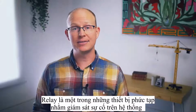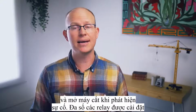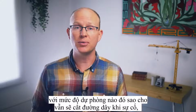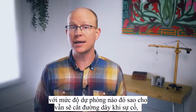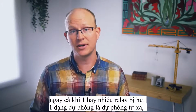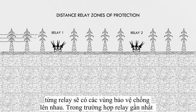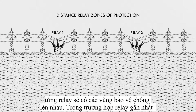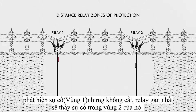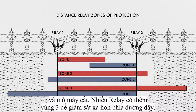Relays are sophisticated instruments that monitor the grid for faults and trigger circuit breakers when one is detected. Most relaying systems are built with levels of redundancy so that lines will still be isolated during a fault, even if one or more relays malfunction. One type of redundancy is remote backup, where separate relays have overlapping zones of protection. If the closest relay to the fault, called Zone 1, doesn't trip, the next closest relay will see the fault in its Zone 2 and activate the breakers. Many relays have a Zone 3 that monitors even farther along the line.